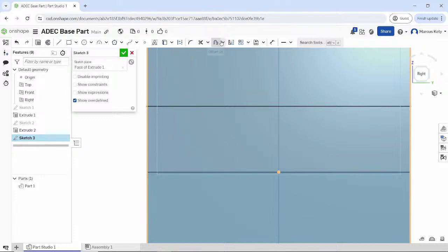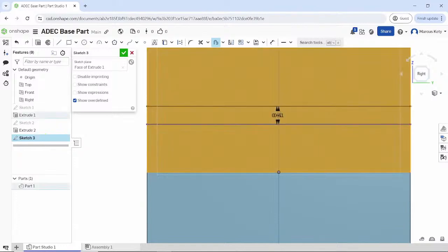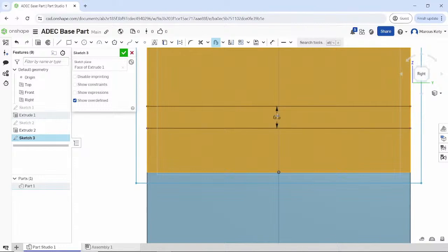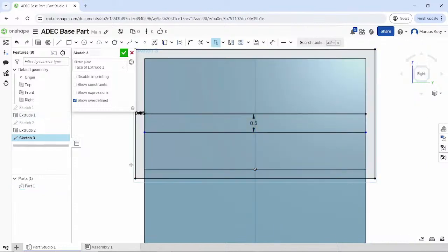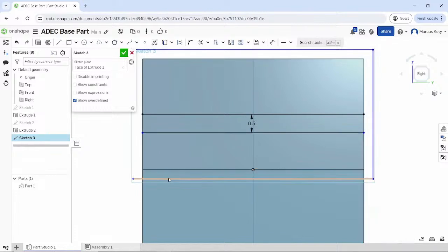We have an option of offsetting the line right here, because we were talking about thin extrudes before. Another way of doing that is to come into this offset and select that, and it's going to ask you which side you want to offset it, and I can click and drag this either way I want, or I can click this number right here. It looks like I have selected the whole face instead, and make it 0.5. I did, in fact, select the whole face. So we're going to unselect this and delete those excess ones.